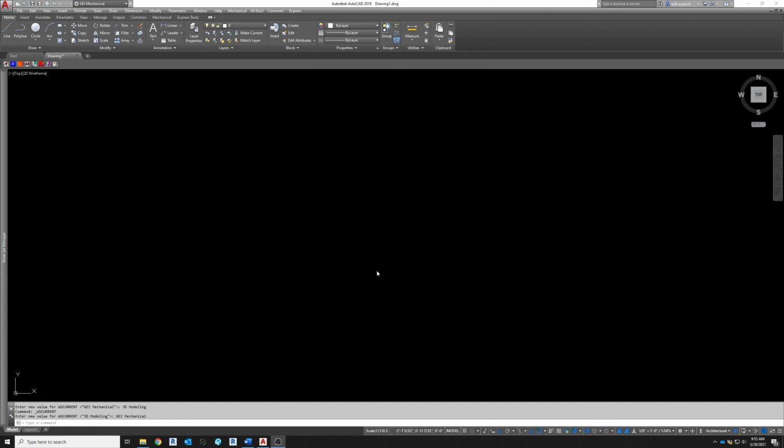The purpose of this video is to go over the AutoTable feature that we use to bring in our mechanical schedules from Excel directly into AutoCAD. AutoTable allows us to bring these directly in from Excel with the information linked between the two so that engineers can be working on information and updating it without interrupting the workflow of the production staff.